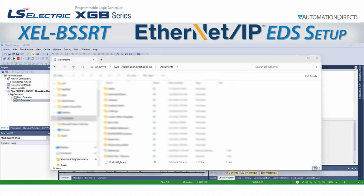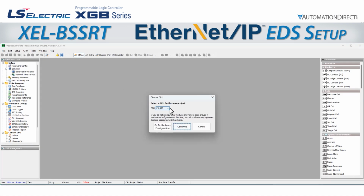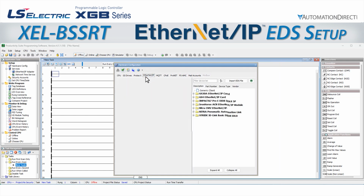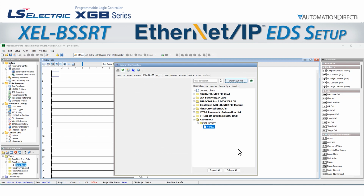I will open Productivity Suite version 4.1.1.10. We will start a new project and select the P1550 as our PLC. We can then click Go to Hardware Configuration. It creates a new project and opens the Hardware Configuration window. If we go to the Ethernet IP tab, on the right side is the EDS file library. There are some pre-installed options, but we want to click Import EDS File. Let's go to our Documents folder, and there is our BSSRT EDS. We click the EDS file and then click Select. It added the XEL-BSSRT as a new device, and has version 1.2 of the file available.